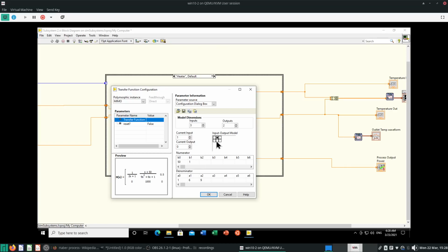At the bottom here, this will be the heater power output. I just randomly give it 1000 watts. So this second column here is actually heater power fraction, and it will translate to a temperature output and a power output. Very simple. So there's nothing too much to it. I just use this multiple input, multiple output to show you an example how it works. And of course, for this case, the inlet temperature will not affect heater power, and of course the temperature disturbance will not affect heater power. So both of these gains are 0. And I put 1000 because I assume the heater is 1000 watts.